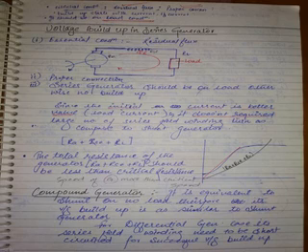Now, listen. Let us consider a series generator, to whose poles you did field flashing, therefore some residual flux is there. Now you start rotating the machine. When you start rotating, the armature conductors will cut that flux, and what is produced? EMF is produced. How much? Let it be 6 to 8 volts. Now, will there be any current flow in the machine? No, because this is a series machine which is open, no load. So even though there is 6 to 8 volts, the circuit is not closed, so no current will flow, and it will remain like that only.